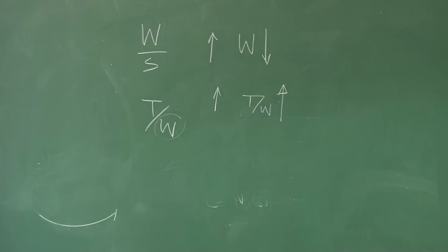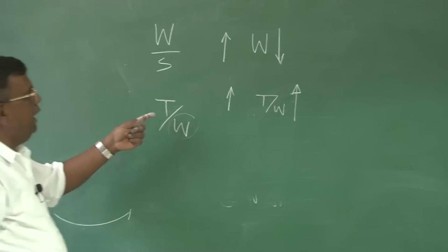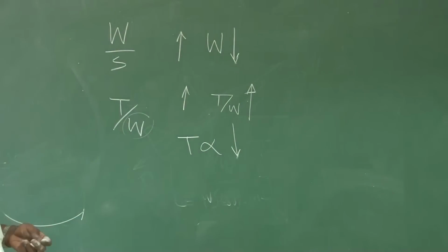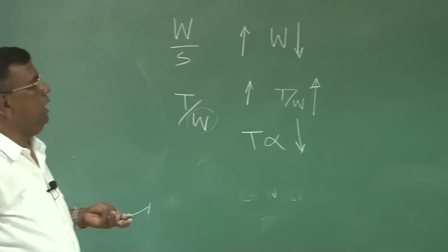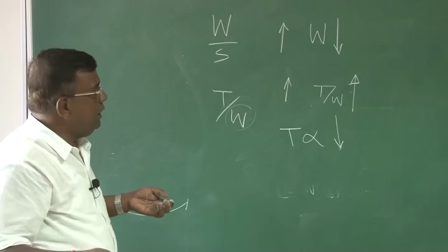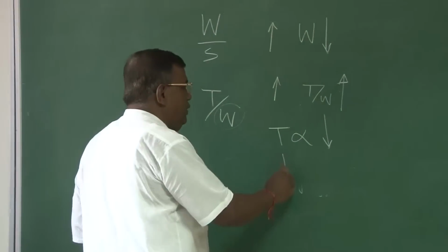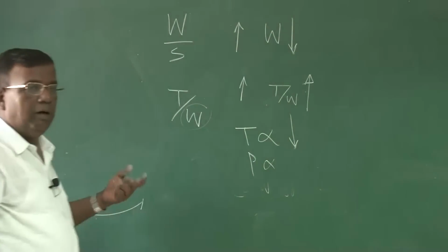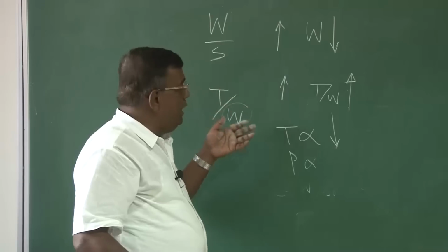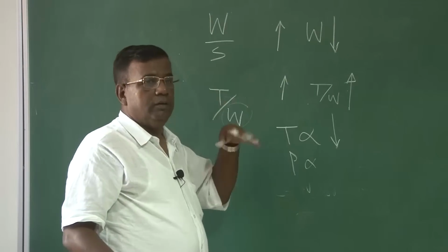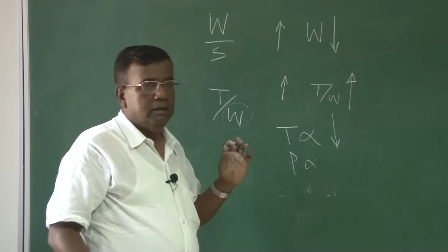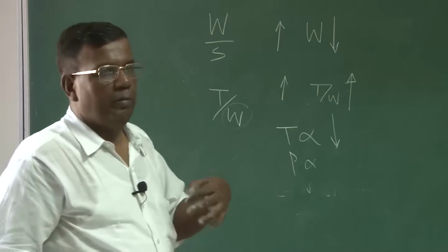Then there is another thing: as I am going higher and higher, the thrust will also drop. Dynamic thrust will drop. If it's a propeller-driven airplane, you could see that the density of air outside will reduce, right? So the thrust available from thrust or power, when you talk about a propeller engine, you know that we talk in terms of power, and thrust means jet engine. So as I'm going higher and higher, the thrust part also will vary with altitude. So as a designer, I need to know how much it will change and keep that as a margin. So it is always better to have excess margin on this.